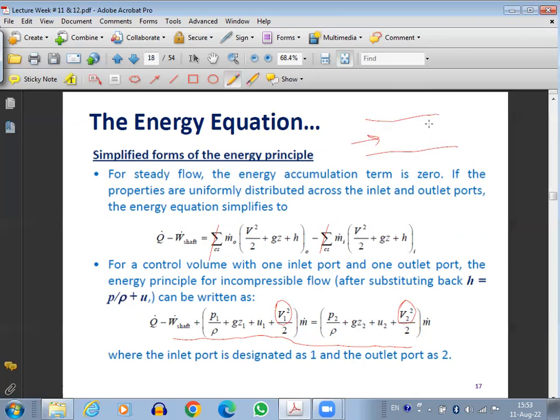We know that there is a specific velocity profile which is generated, and it looks something like this, where the velocity is maximum in the center and at the edges the velocity is 0. Because of the no slip condition at the edges of the stationary pipe, the layers of the fluid at the edges are also stationary, and the layer of the fluid in the center has the maximum velocity.